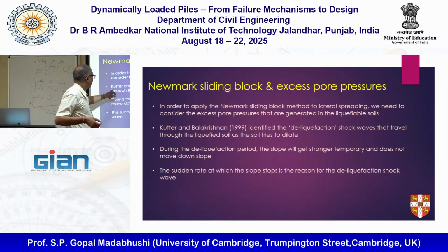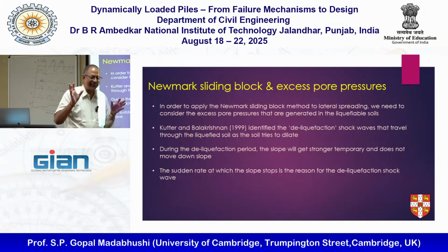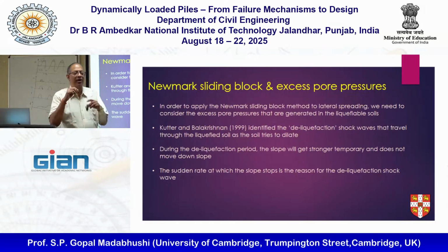Cutter and Balakrishnan had even bigger, grander ideas of trying to link this. Yesterday, I mentioned that when the soil fully liquefies, if you try to shear it, it will undergo dilation. And the dilation expresses itself as a deliquefaction shock.